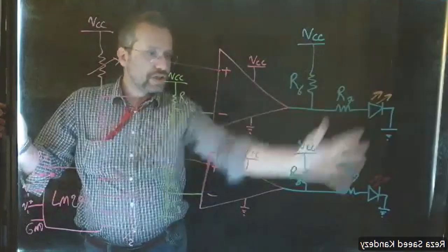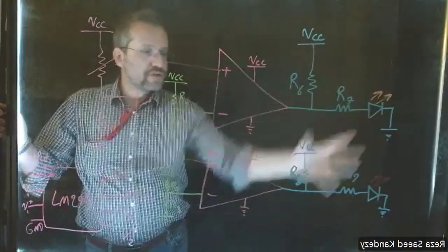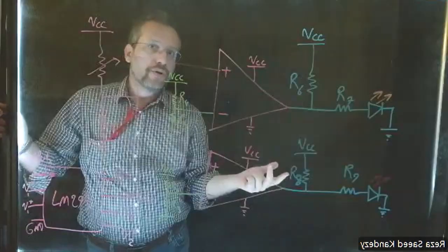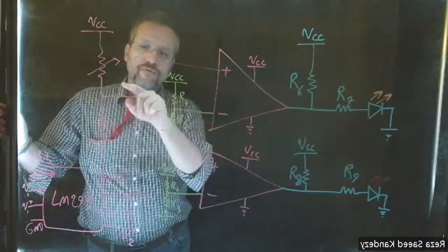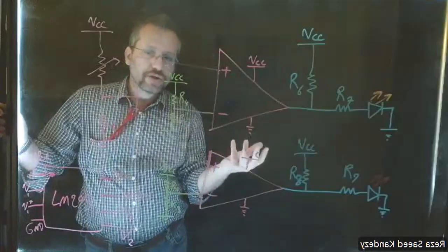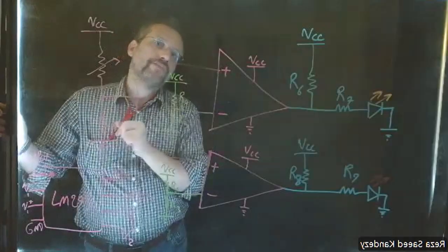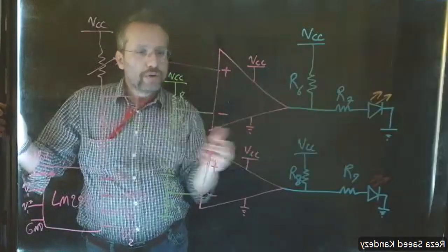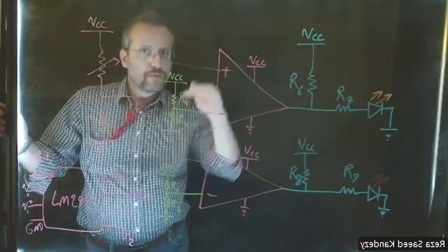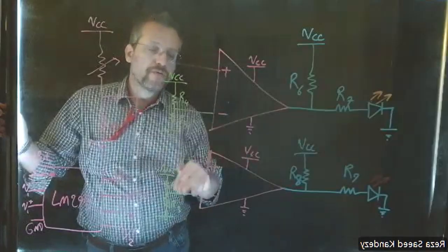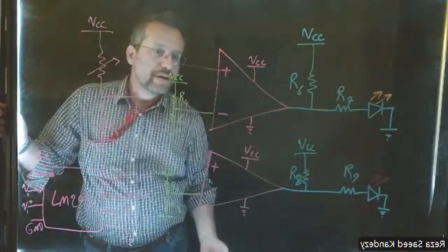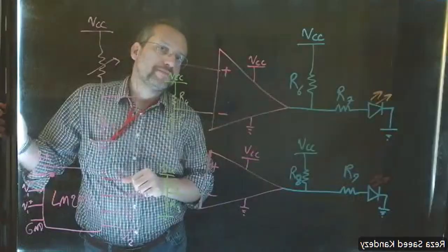So these double sets of comparators create two indicators by comparing the input, which is the electrical signal translation of the difference in temperature, with two sets of references, one set to define the warm level and one set to define the hot level, and then turn on the LEDs based on the temperature.